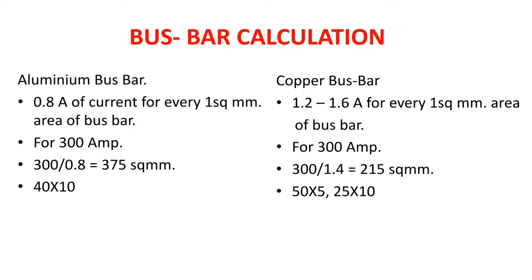Okay, before going further in this calculation, friends, what do you think? On which factor does this busbar calculation depend, and which two dimensions of busbar do we take for calculations? This I have already discussed in my previous video, but don't worry, I'll answer both the questions here. Friends, busbar calculation depends on the current value, that is how much current is flowing in that busbar, or how much load this busbar has to take. And the dimensions of busbar we take are its width and thickness, not the length.